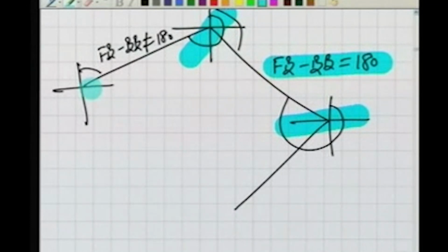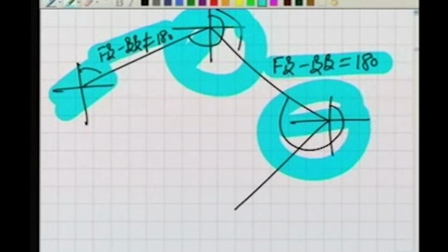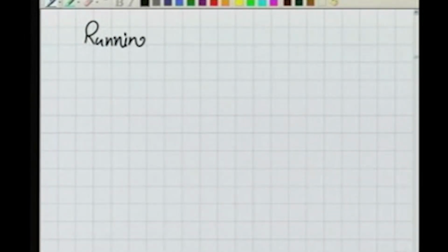So, our conclusion will be that this station has the local attraction because of this. We know now that our stations here are free of the local attraction, while this station has the local attraction. And having known this, we can accordingly apply correction for the local attraction, which we will see in a moment. Now, before we go into the corrections for the local attraction, let us talk about running a compass traverse.